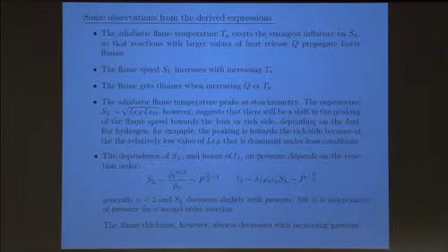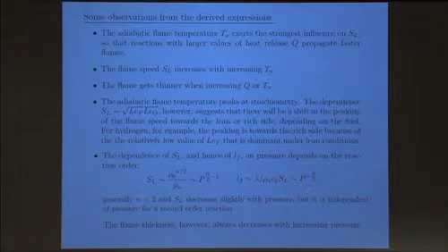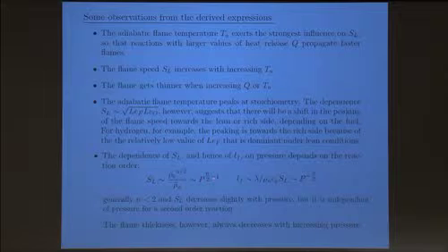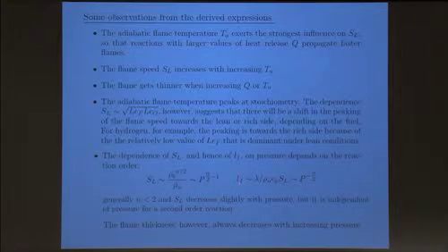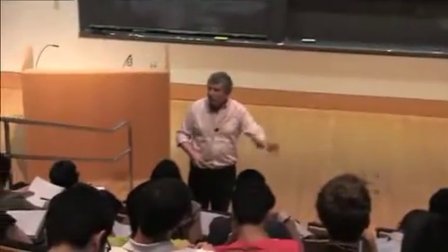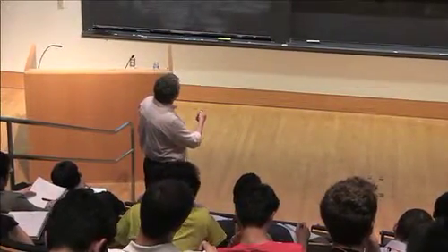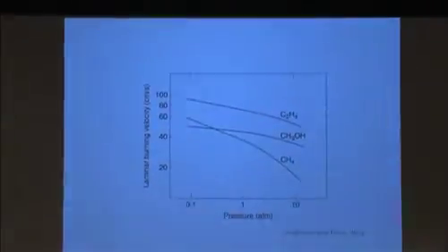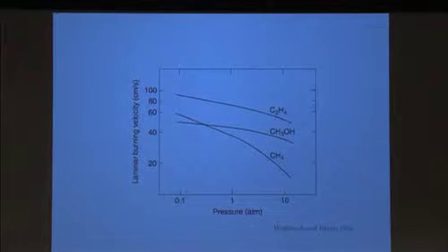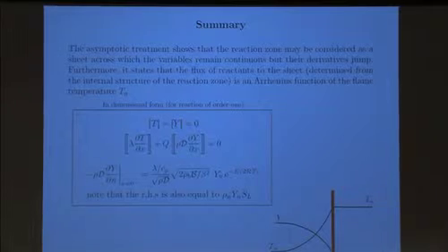However, the flame thickness will always, because there is an additional rho here, and therefore it kills one of this minus 1, the flame thickness is proportional to the pressure to the negative n/2, and so therefore it will always, irrespective of the reaction order, decrease with increasing pressure. And you can see, for example, the result here of the burning velocity as a function of pressure, showing a decrease for a wide range of pressure. Okay, so in summary,